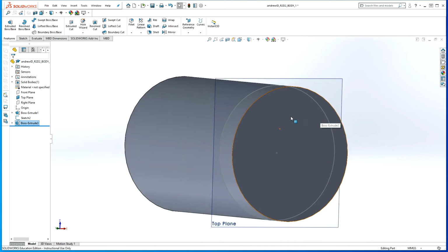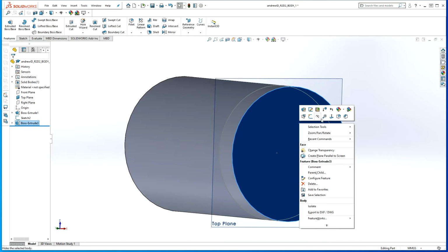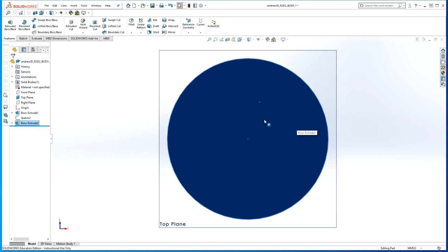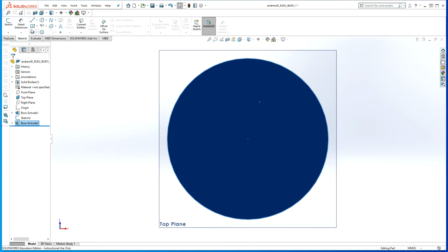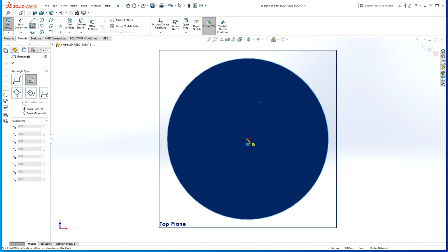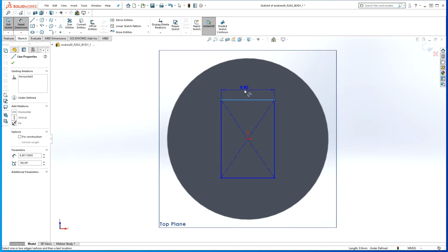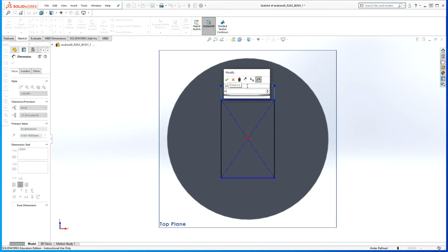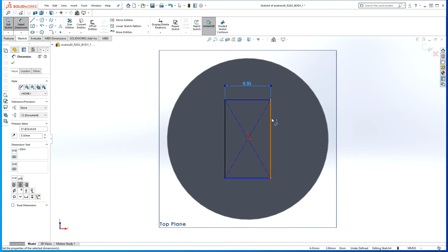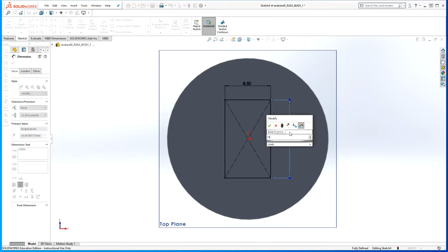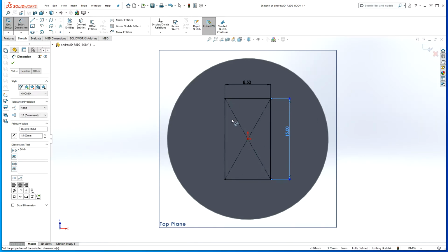So again, I've extruded that sketch. We've just lengthened the cylinder by 5.5 millimeters. We're going to go again normal to the bottom of that extrusion I just made and select center rectangle. The origin is what we want to anchor to, so my first click will be on the origin, which centers this, and I'm just going to arbitrarily click a size. I'll go to Smart Dimension, make the top 8.5 millimeters wide, and then the height of this 15 millimeters. I don't need to dimension anymore.